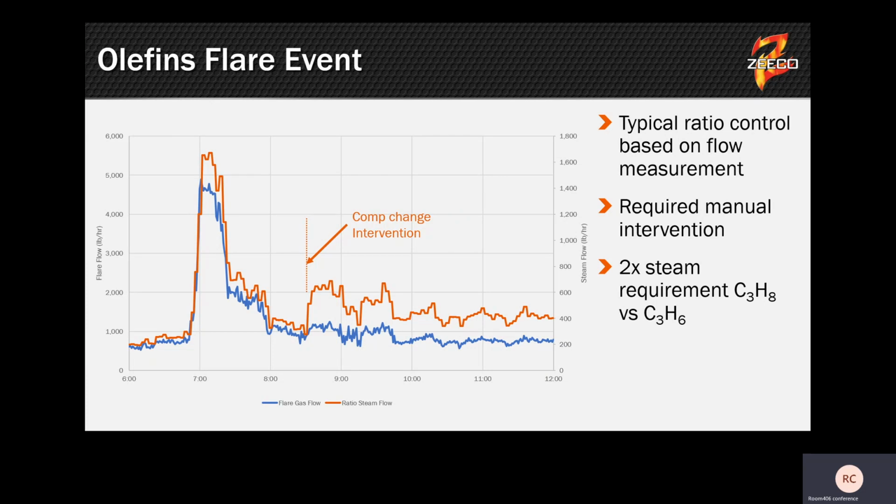The problem is, as the nitrogen was pulled out and we got to a lower rate, we see this many, many times. The event is largely over, and operators can now concentrate on whatever process they were trying to control, until somebody finally looks at the CCTV and realizes that I've mitigated the flow, but they're still trailing smoke. And it's because there's residual olefins left in there.